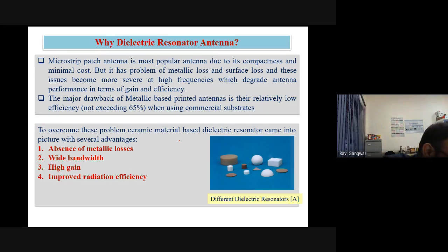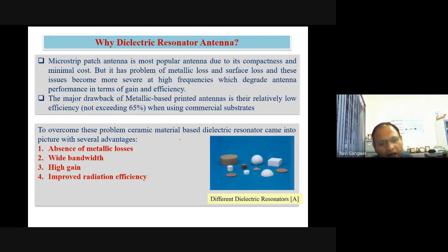So what Professor Stuart Long did was change something. First they removed the metallic enclosure and used a simple piece of ceramic material. And they reduced the dielectric constant of that material. Because by the definition, the permittivity or dielectric constant gives information about how the material permits the electric field, that is, how capable the material is of holding the field. So when we reduce the value, we reduce the capability to hold the charge or the field values there.